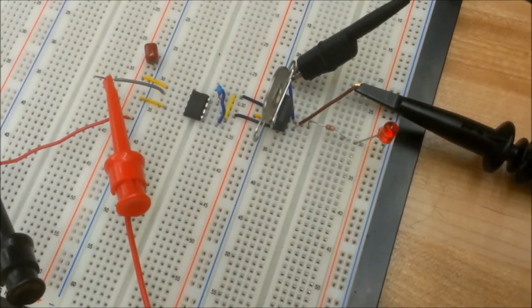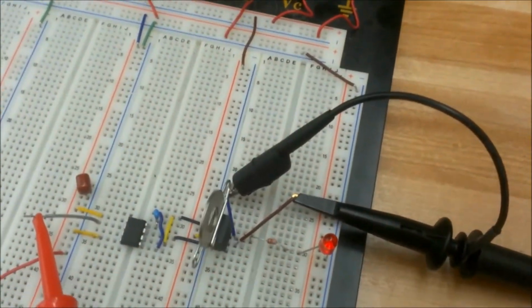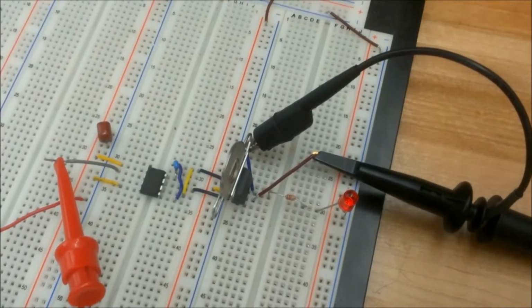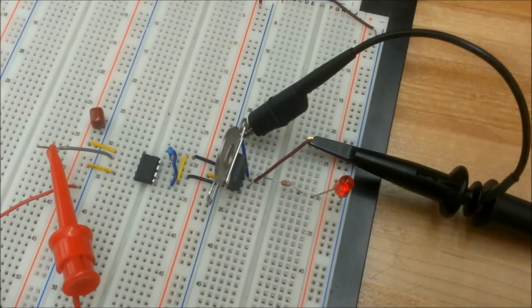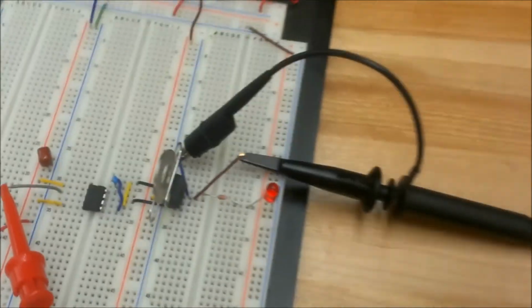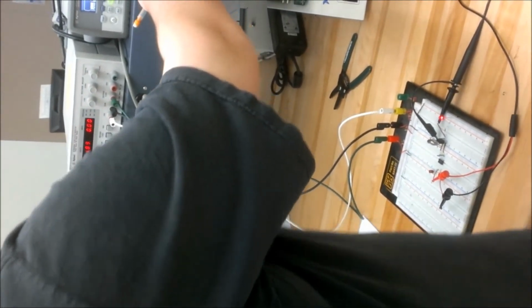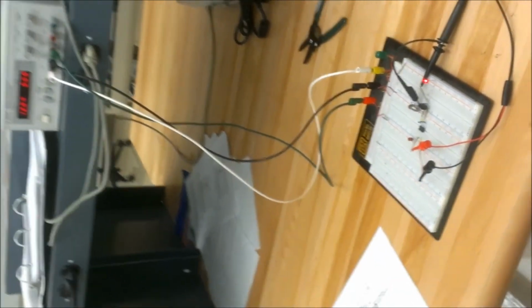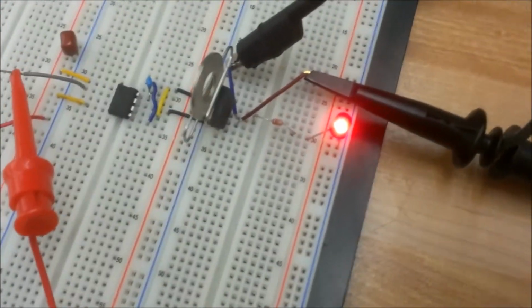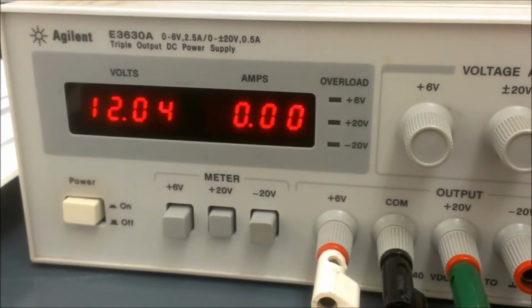We'd like to note our homemade heatsink with a washer and a paper clip, because we are inventive engineers that don't need to spend lots of money on heat sinks. Kind of like Dr. Koh and his liquid stitch. Now we are going to turn on the DC power supply and function generator, and as you can see, the LED lights up. This indicates that the load is getting a voltage. I would also like to note that this particular gate driver requires a 12 volt input to operate.